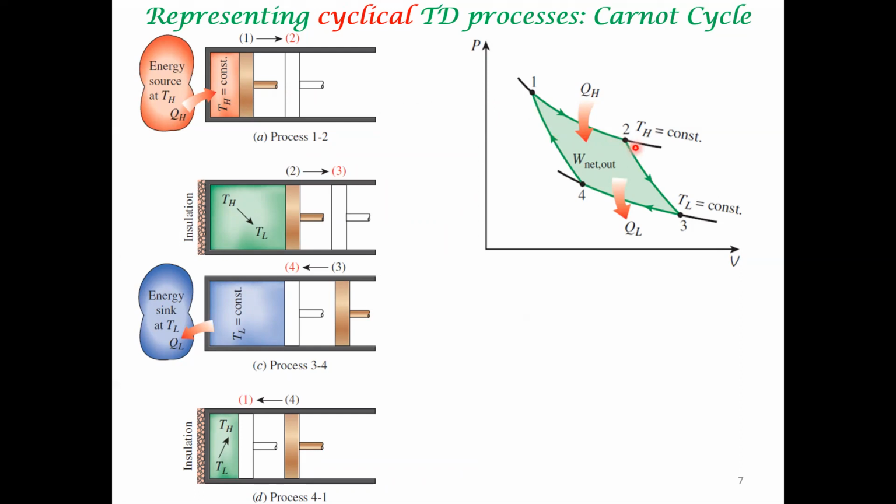So just to build your intuition, always imagine all these things occurring via an ideal gas. That's not a necessity because we earlier proved by Carnot's second principle that all this Carnot analysis is independent of the fluid you use.